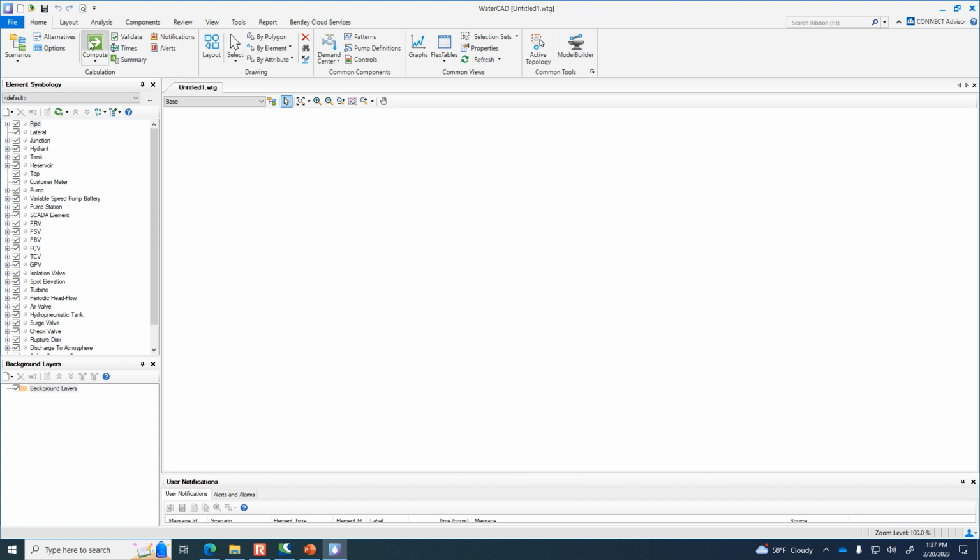So here across the top in the ribbon, there's this layout button. If you click on the layout button and then bring the cursor down into the main menu, you'll notice that the pointer has changed. Right now, that is the symbol for a junction. So I'm just going to click in some location, and that's going to be junction A. Move some distance away.